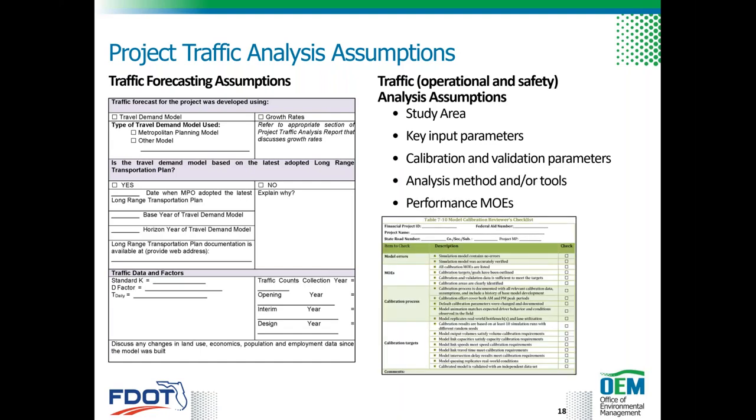Quality control review for traffic analysis results should include reviewing methods and assumptions used to develop the analysis, the inputs, reasonableness of results, and completeness of the results. The assumptions used to prepare the traffic analysis, including traffic projections, should be documented so that the reviewer can easily understand the methodology, input values, analysis results. The traffic analysis assumptions are discussed and agreed upon during the development of the methodology.